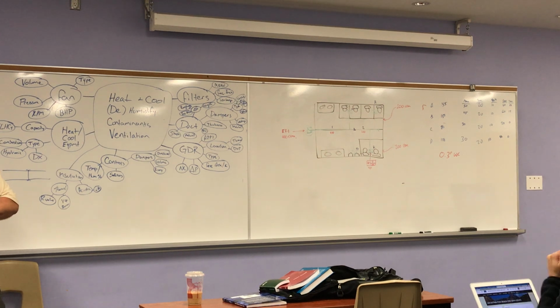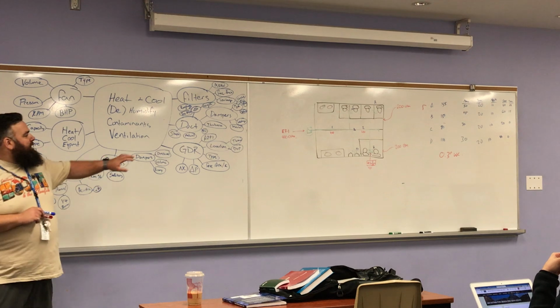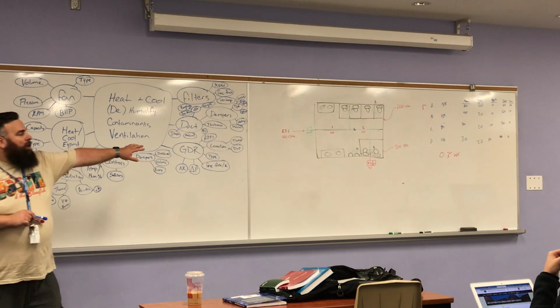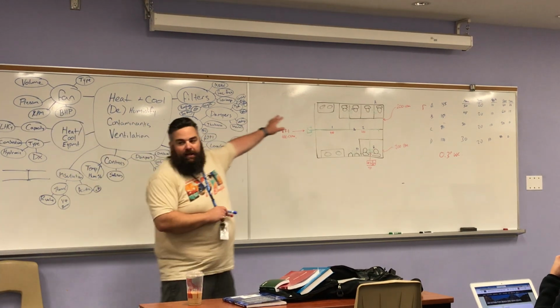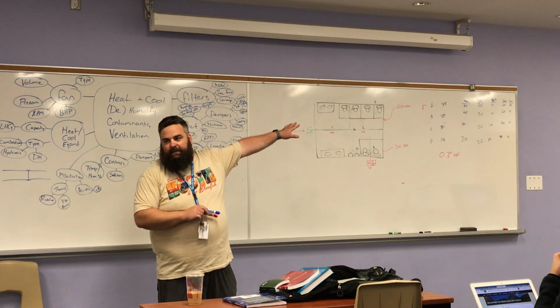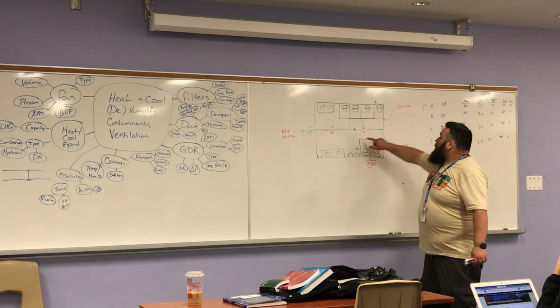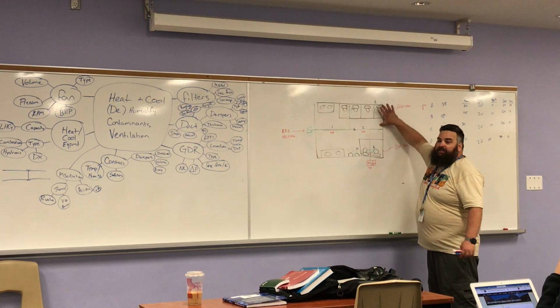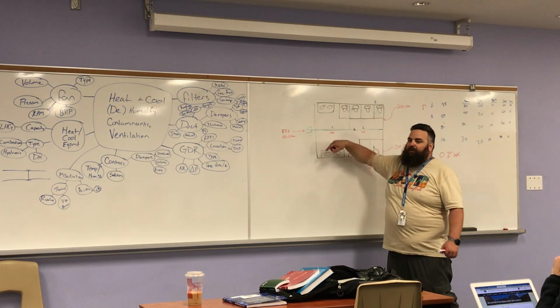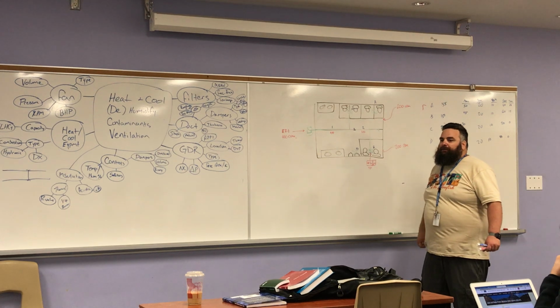It has to be the same pressure drop for every branch. That's going to be my total, and that's measured based on the longest run. That's what dictates it. With the idea being, if I have enough pressure to overcome the resistance of this, I have enough pressure to overcome the resistance of the rest of it, because they're going to be less restrictive.